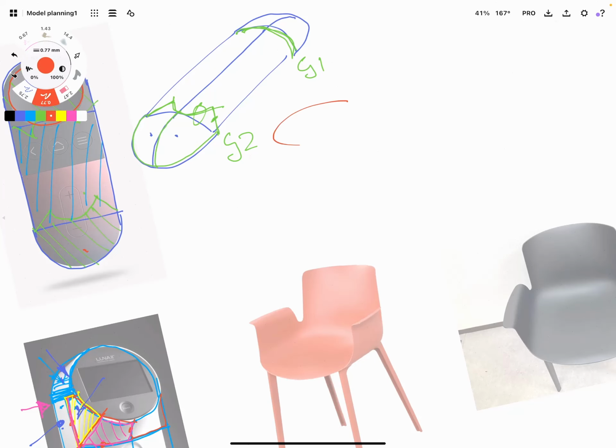You could arguably go like this, so you create a center line, then you create some sections going in the other direction, and then you build your first surface there, and then you do what I did on the ends here with the green. You basically trim that area out and then make a four-sided surface in the ends there.